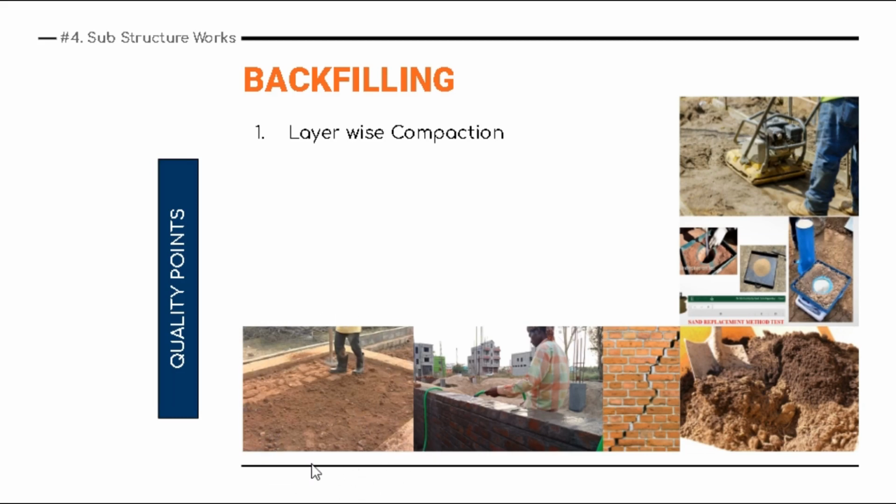Okay, so next is 6 to 7 days curing of all substructures. Many times in the business of construction we never follow to cure the substructure points, so this is quite essential and important as well.